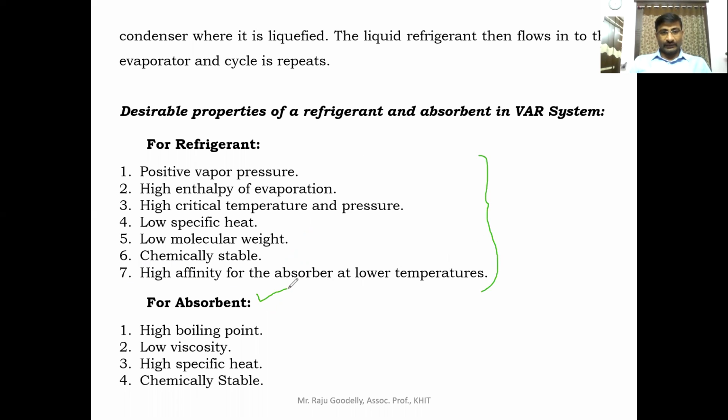Then absorbent means this is the fluid which absorbs the refrigerant at lower temperatures. This absorbent must have these good properties. High boiling point. The boiling point must be above the refrigerant.